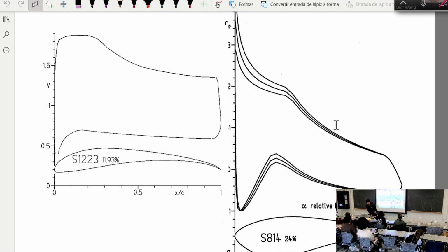This two-stage process is actually because the designer of this airfoil fully expects the boundary layer to have transitioned into turbulent boundary layer before this point. Okay? That's the reason after this point, it is okay to make the pressure gradient steep again, because once the boundary layer transitions into turbulent boundary layer, it is more resistant to adverse pressure gradient.